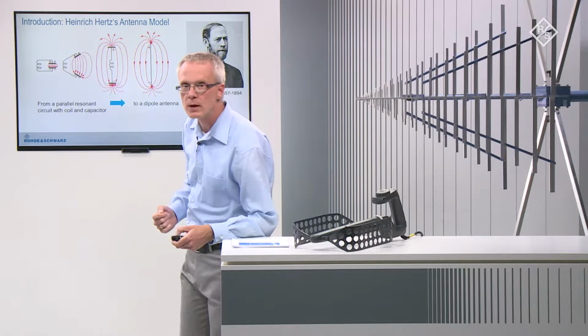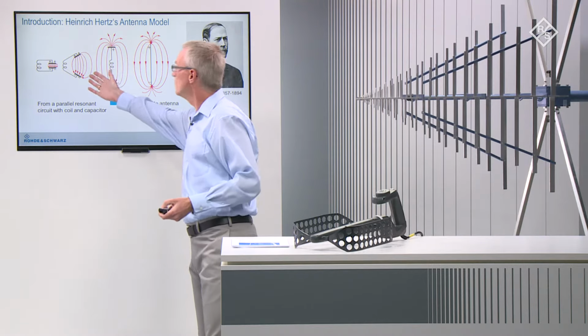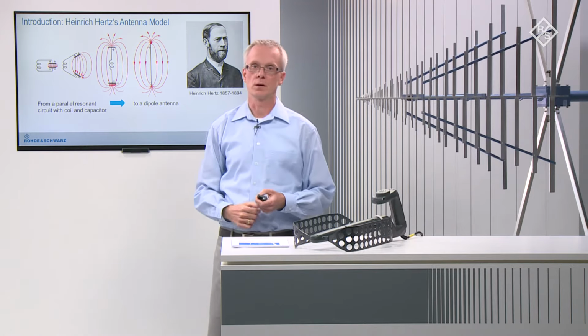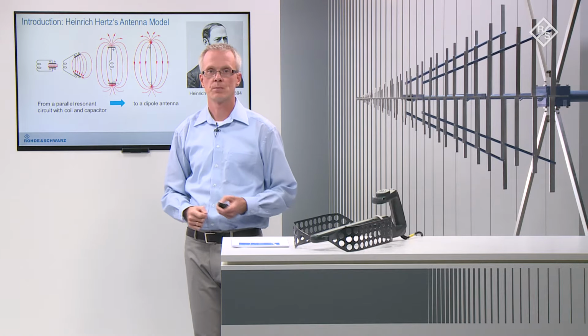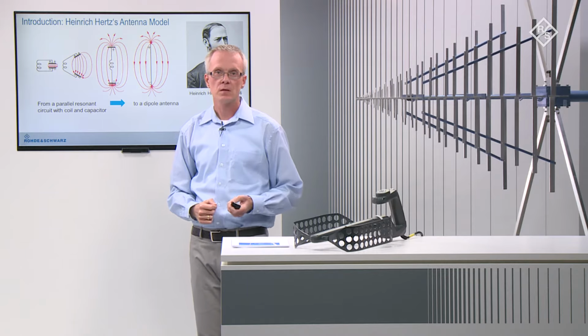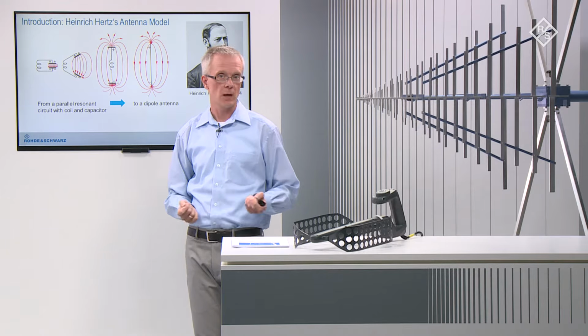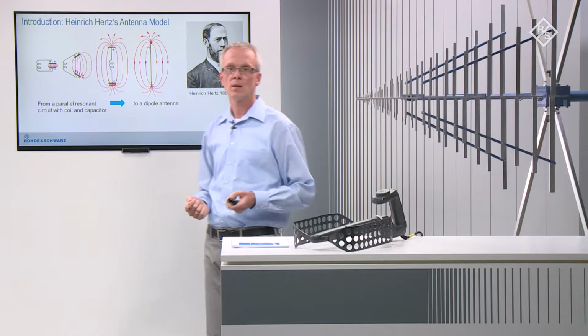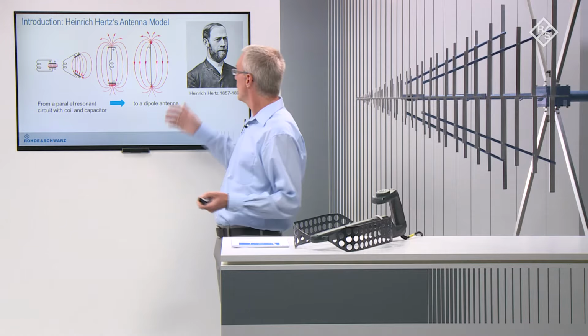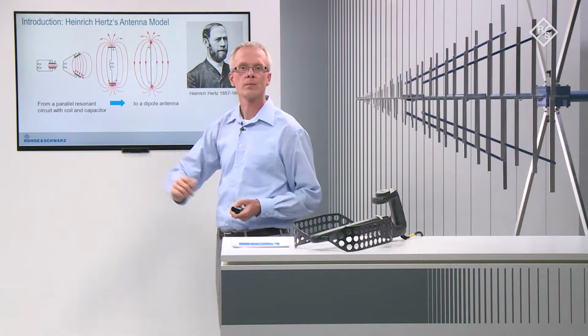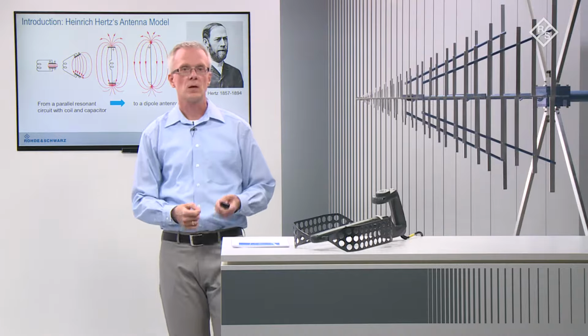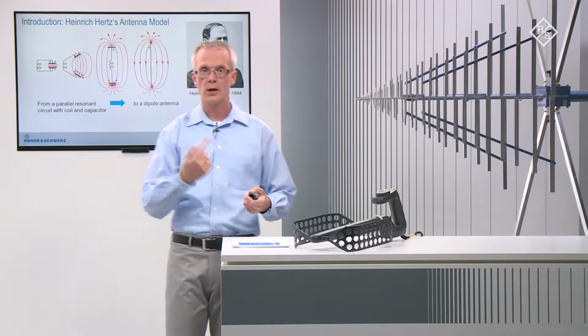If the capacitor plates are now bent open, an inhomogeneous field is created between the tips. For increased frequencies, the inductance of the wire and the capacitance between the tips of the dipole is sufficient to get the electric field shown at the very right position, which alternates with a magnetic field circularly around the dipole.